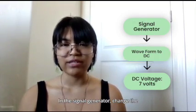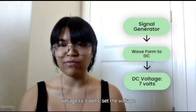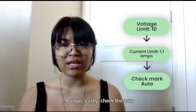In the signal generator, change the waveform to DC, set the DC voltage to 7 volts, set the voltage limit to 10, and the current limit to 1.1 amps. Lastly, check the auto box.